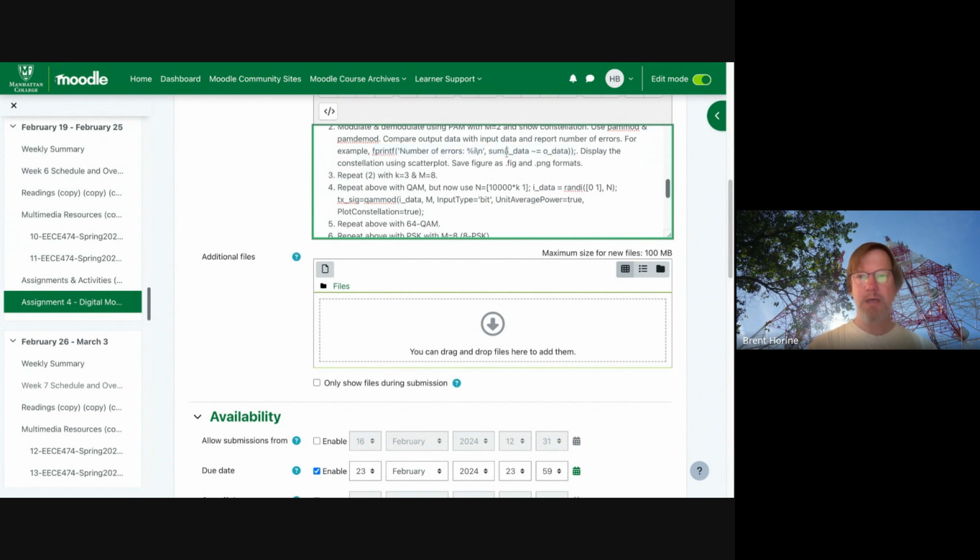So you can do something like this. You can create the input data, calculate the output data, and then check them, right? MATLAB will operate on a matrix or vector level when it's possible. Since both I data and O data, the output data, are vectors, this statement will compare all of those element by element.